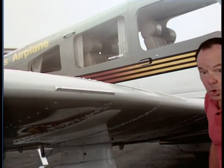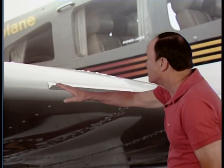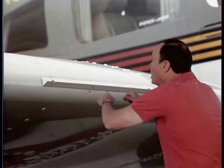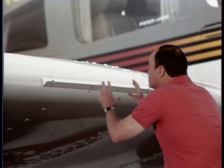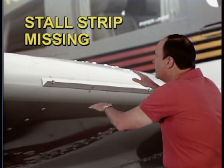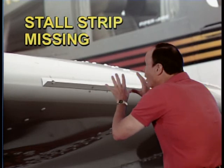Now, if you want to make sure a wing stalls near the wing root first, you install this. It's called a stall strip. And at high angles of attack, this stall strip causes the air to burble here near the wing root first rather than out at the wing tip, and it creates the stall here first. So if you happen to be pre-flighting an aircraft or doing some work on it, and you notice that all or a significant part of this stall strip is missing, what's going to happen is the stall won't be the same on each side of the aircraft. It could stall at the wing tip first instead of at the root on this side of the wing.